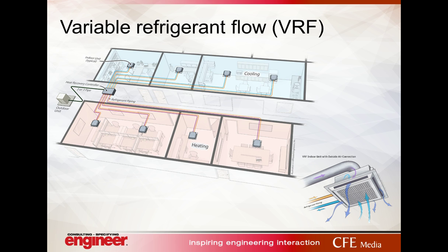And now, when you're in this heat recovery mode with simultaneous heating and cooling, the great part that helps with efficiency is that you only have to pay for one of them. So whatever the predominant load is, you pay for the compressor energy for that, and then there should be enough potentially recovered heat, hot gas coming off of those evaporators, to be able to divert to the zones that need heating. So you're really only having to pay for that once. So that's a big efficiency gain.